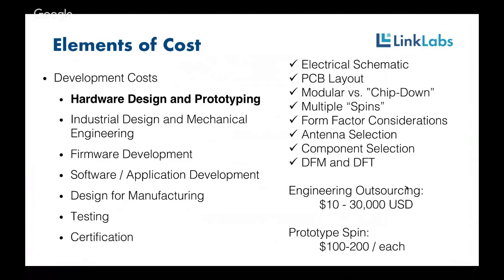The PCB layout's also important. The number of layers in your printed circuit board and the complexity there, again, those affect the cost. We always talk with a lot of customers about using a modular approach to electronics versus a chip down design. So in a modular, you've taken a little subsystem like a radio system or a power system that another vendor has done all of the R&D to put the parts down on it, all the testing and productization of that module, and then you put that module as a component down on your board.